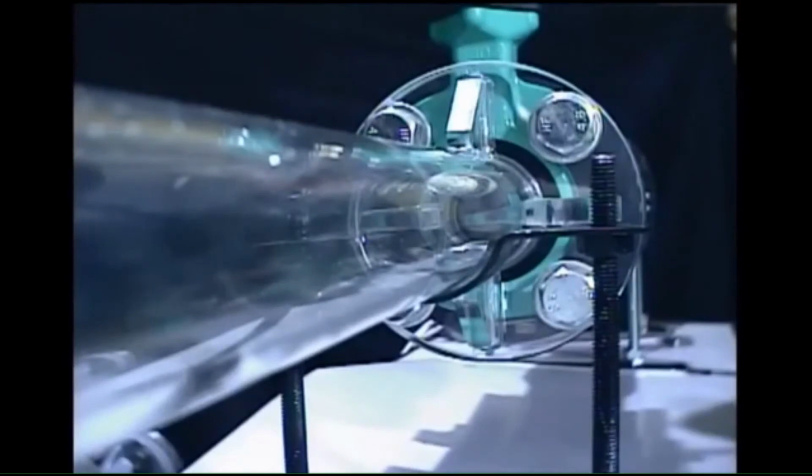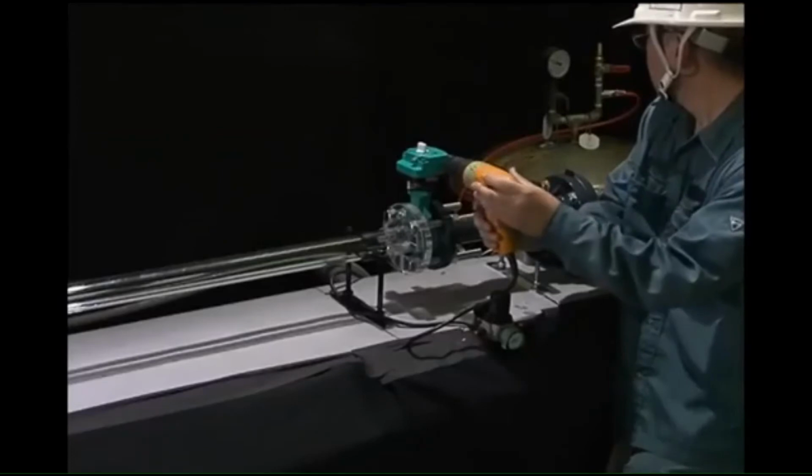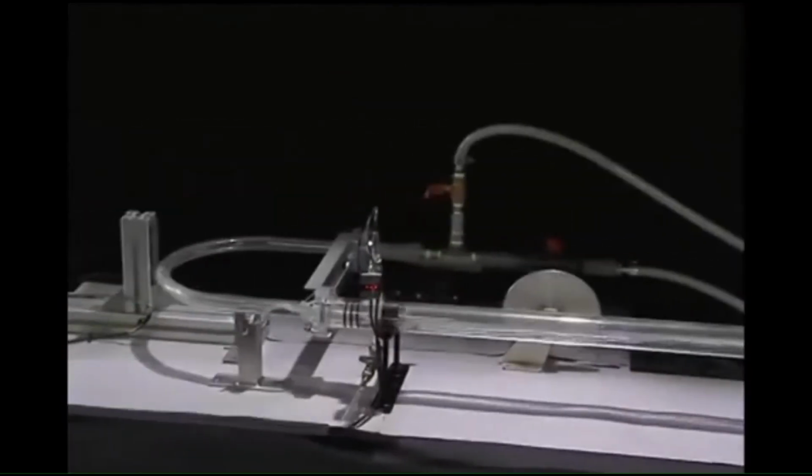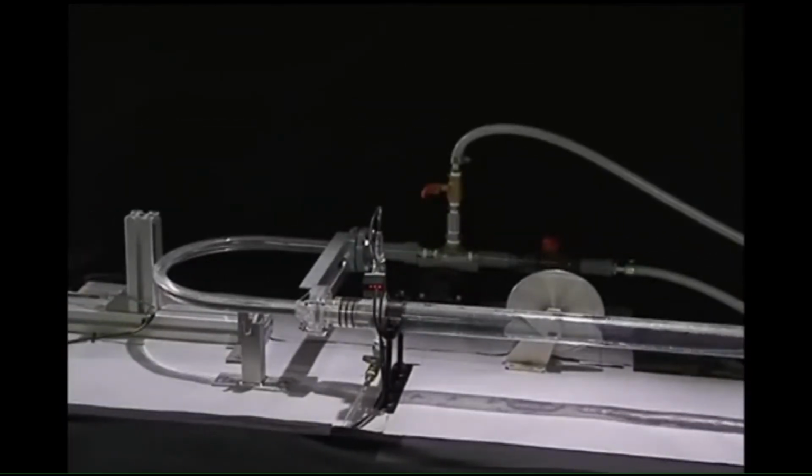The section of the acrylic pipe from the valve beyond is of negative internal pressure. In actual ballast operations, there are cases where cleaning with an eductor is carried out in the final stage, which calls for the ballast line pressure to be negative. This equipment simulates such a condition prone to accidents.